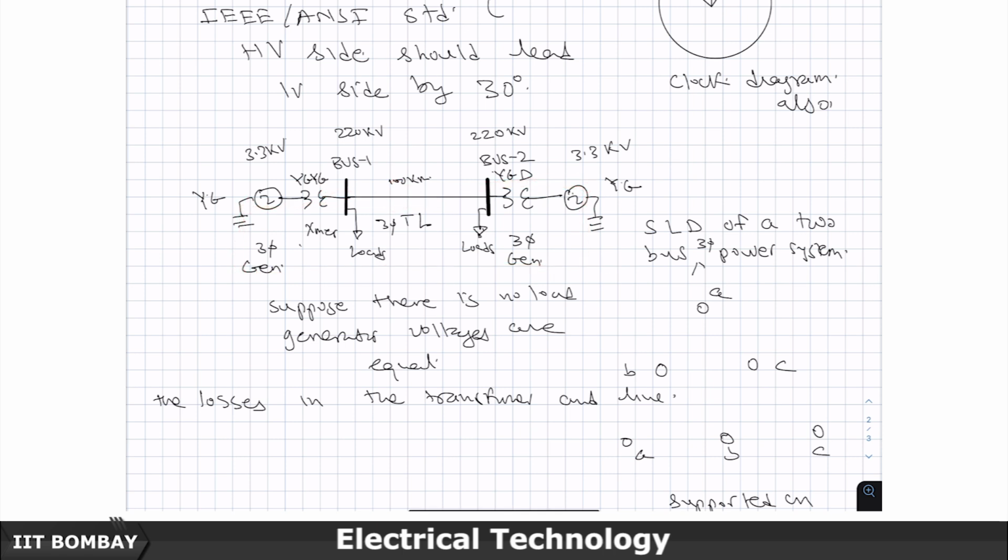So, if there is a path for flow of the current, then obviously, if the magnitudes are different, current will flow, losses will happen, and you can see that even when the system is unloaded, there is no load connected, the generators will need mechanical input power to sustain the losses. This is an asymmetric operation which is undesirable, because in a balanced condition with nothing loaded on it, you would like to see everything symmetric, currents being 0 and so on and so forth.